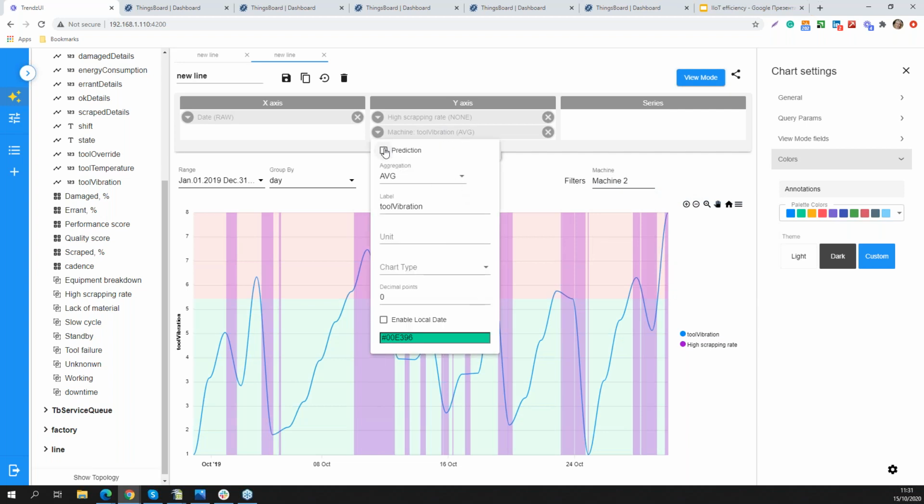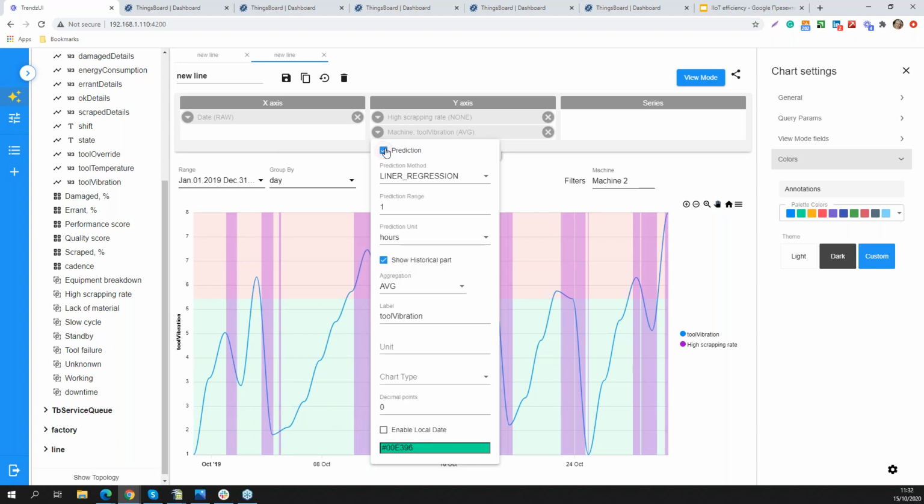We definitely spot the correlation between the amount of scraped details and vibration, but we would like to predict the values, to predict how that machine will behave in the future, to know whether we should replace some details now, or should we wait, or where vibration will be the most critical in the week. So we have chosen the Fourier transformation, which is really good in predicting seasonality phenomena, and we choose the prediction rate of 14 days.